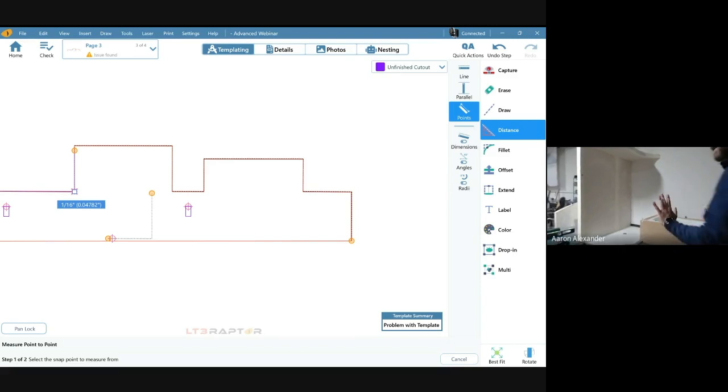So you're setting the plane. All 3 points are on this wall. And then we're aiming onto the boundary objects that create the wall. Onto the ceiling, right onto the back wall, right onto the floor, right onto the outside edge, or we have targets projecting this edge out into space to give us something to shoot on if we want to set up inside here. Then we could move the laser.